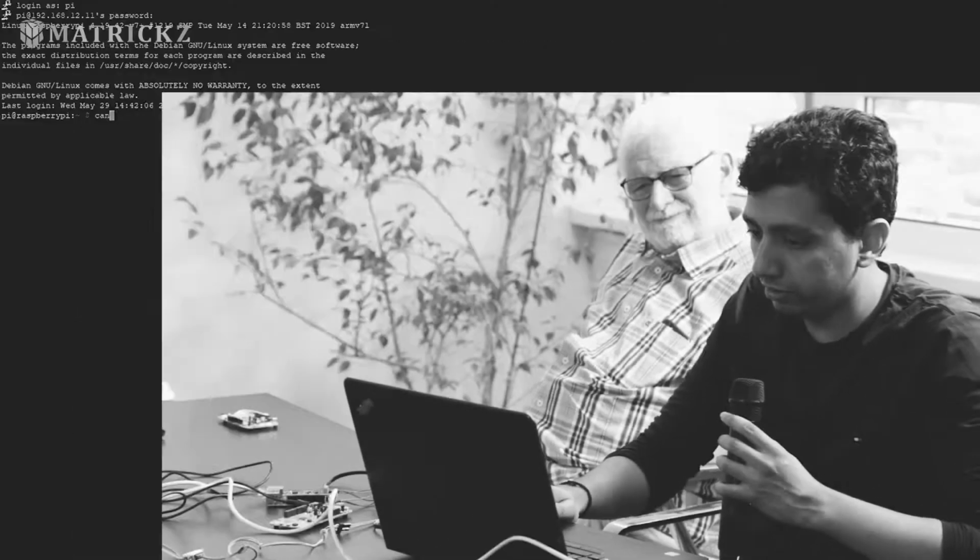Yes. Okay, cool. So for today's demo, we've used Python to program the Raspberry Pi and to use the CAN. We just installed the CAN utils package already available for Python. If I use a CAN dump on the Raspberry Pi, I can see all the messages that are available on the CAN.